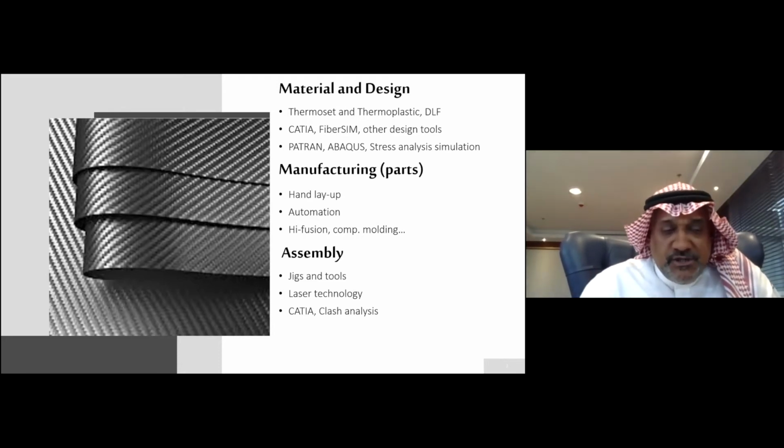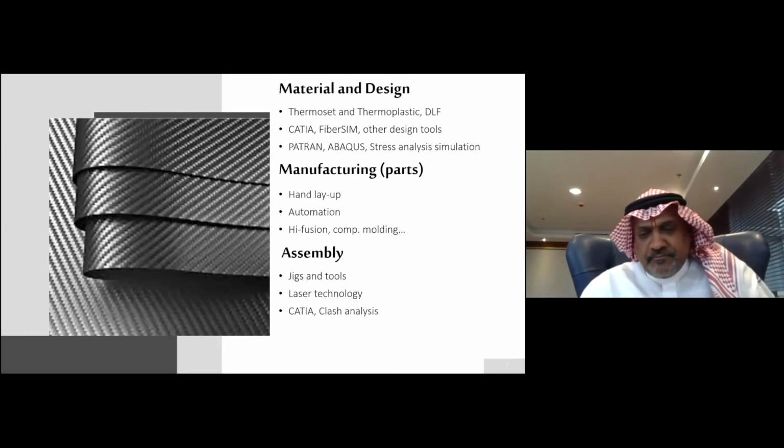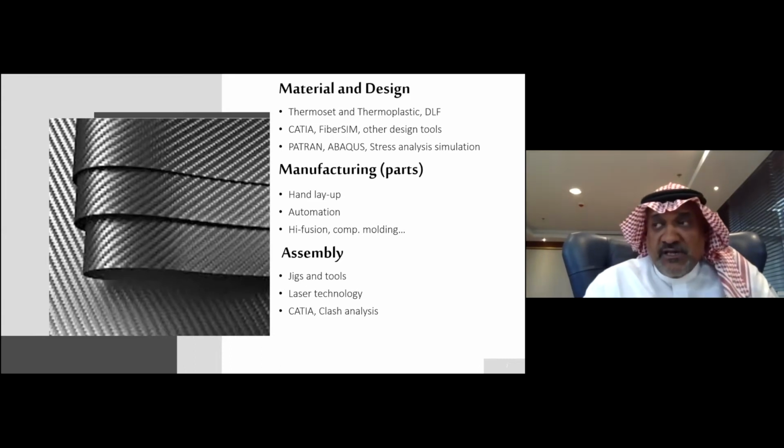That doesn't work in a structural part, because when a composite part gets damaged, you're breaking the fiber, and thus you will discontinue the load in the part. So we have to go to the titanium piece to connect it with fasteners so we can have a continuation of the load. Now, this is a brief about design engineering and composite design in aerospace and structure.